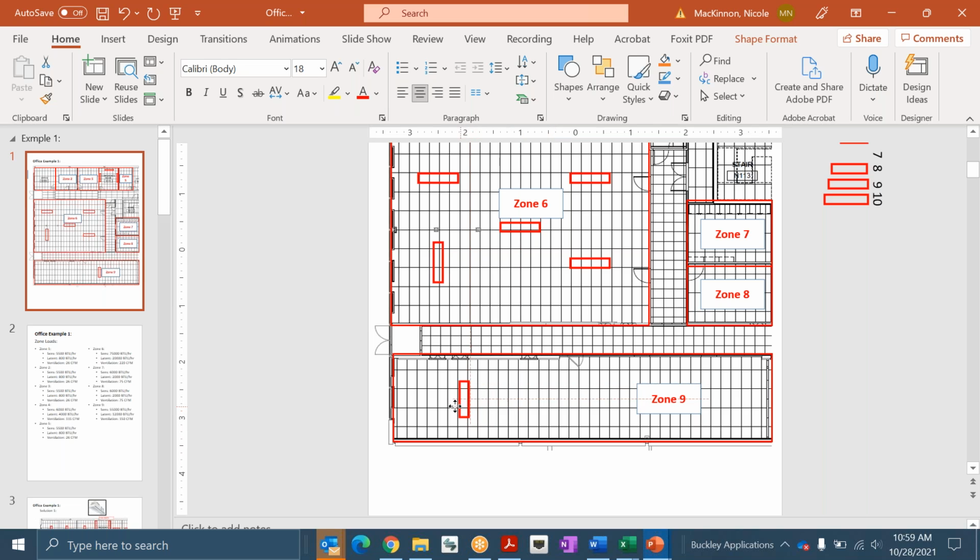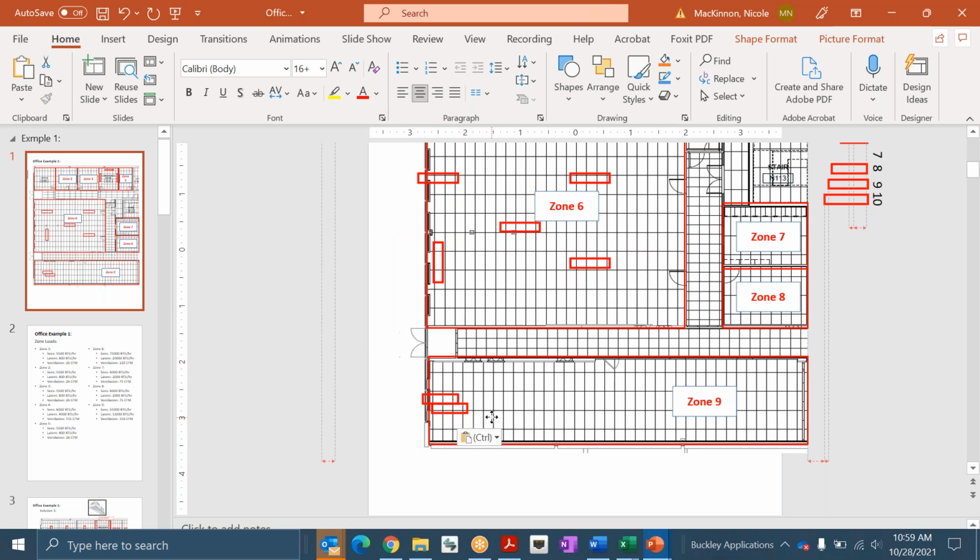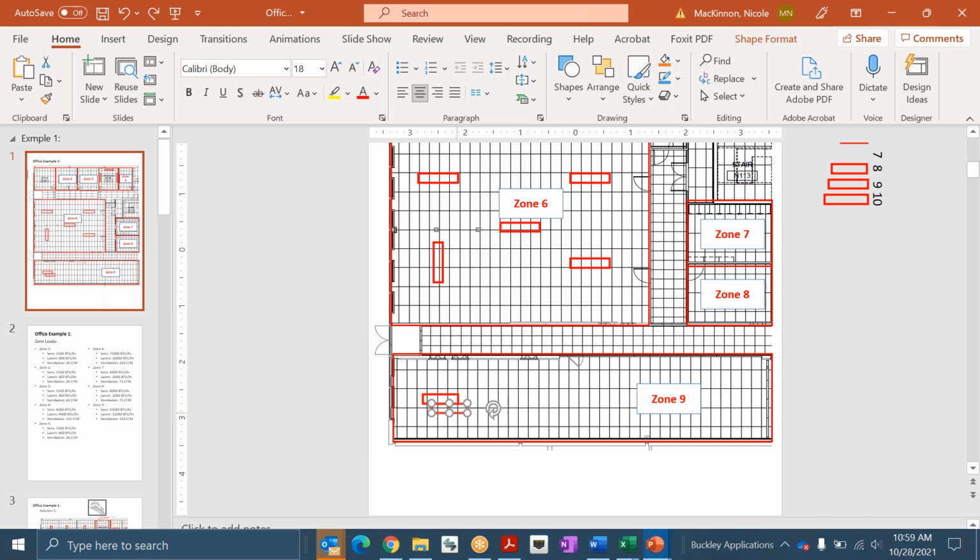I'm actually going to lay this out. There's a few ways you can do this. One thing I like to look at is where is my south-facing wall. I like to blow air on the south-facing wall, and try to take care of some of that envelope load with the beams wherever possible. So that's my thought process in laying it out horizontally. You can absolutely lay it out vertically here as well, but that's just one thing I would like to think about: where are my zones, where are my throws going to be the most helpful.